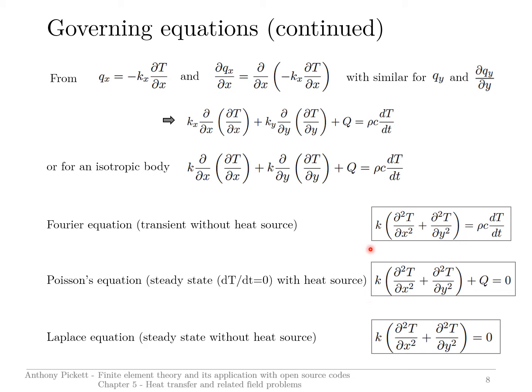Because it's steady state, it means we neglect this effect. And the Laplace equation is a further extension where we neglect internal heating, and we also neglect the mass or capacitance effect here to give us this equation. So these are three variations of these governing equations shown here.